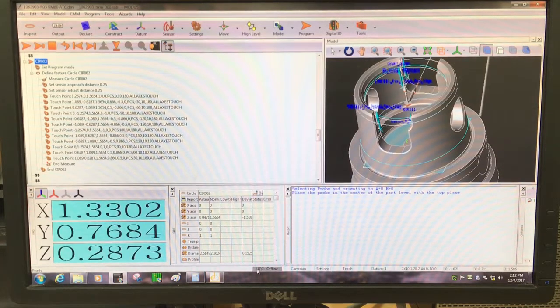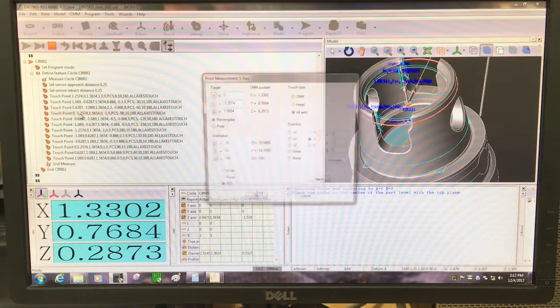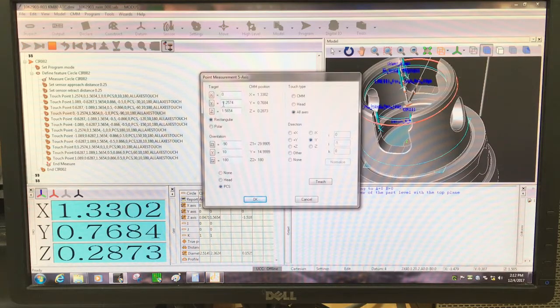Now you can see down here, I can do stuff in the program and the actual machine is not going to move. Now looking for my first x0 coordinate right here, I want to make a movement at that height, just further out in y. So instead of negative 1.2574, I'll just make it negative 2.